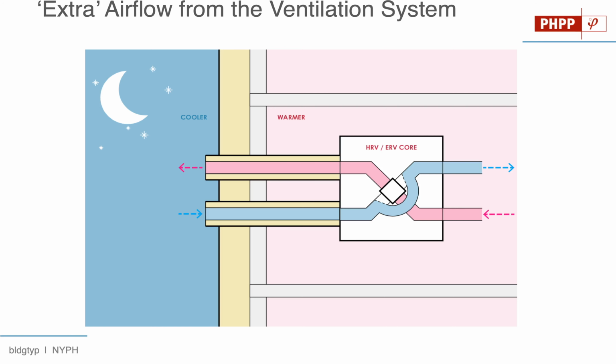Note, of course, that in certain circumstances, in certain climates, taking outdoor air at night and just bringing it right into your building might actually cause more discomfort if you're in a humid climate where it might be cool out, but maybe it's super humid, and just bringing all that moist air into the building might actually increase discomfort. And so, it's not the case that this is super useful all year round in all climates, but it can be useful at certain times of the year and in certain climates. And so having it as an option is useful to be sure.